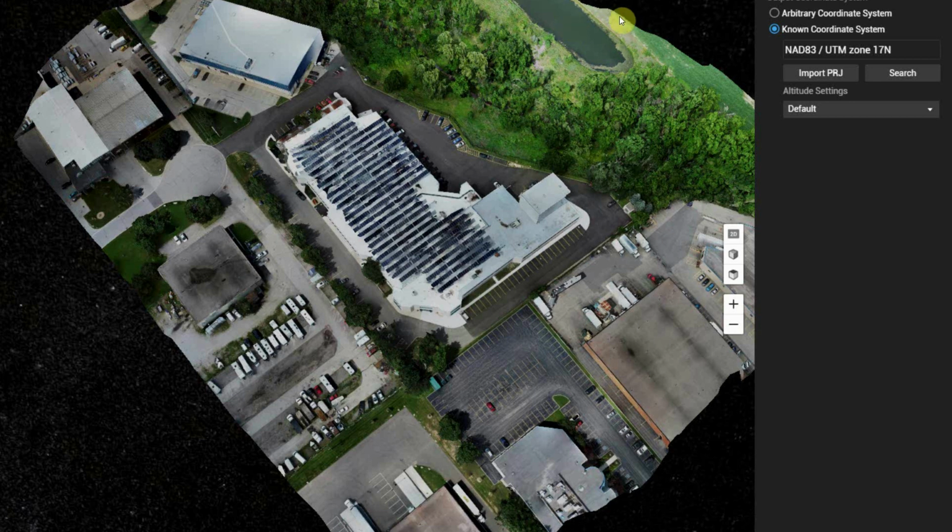You can do this with DJI Terra by setting your output coordinate system to your destination, for example, NAD83 UTM zone 17 north. This is very useful for surveying, construction, and engineering in general, because it provides more flexibility for users to switch between coordinate systems.